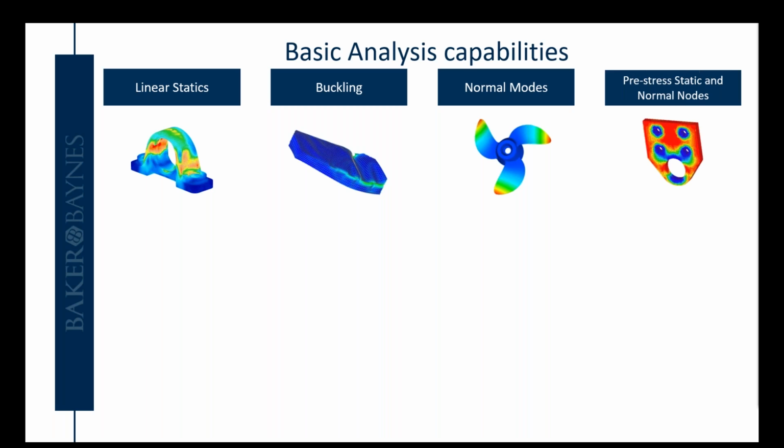You get normal modes. This determines the undamped natural mode shapes and frequencies of structures, allowing designers to explore and resolve problems with noise and vibration. It also analyzes natural frequencies and mode shapes, flexible and rigid body motions, modal participation factors, effective mass or weight, and reaction forces, linear and non-linear pre-stress or stiffening, and virtual fluid mass.